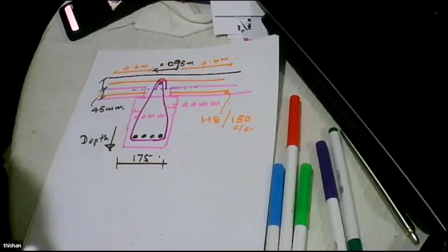And even for a 6 meter span, what becomes larger is the beam, but not the slab. The slab will remain the same, 90 millimeter thickness and continuous over every 2 meters, where there will be either a wall or a beam.